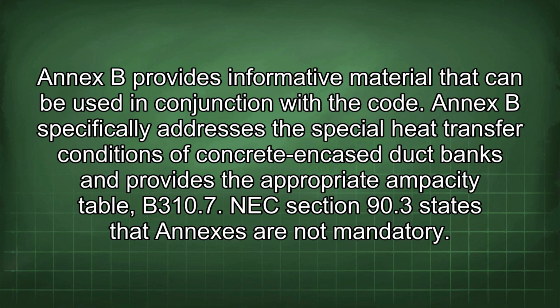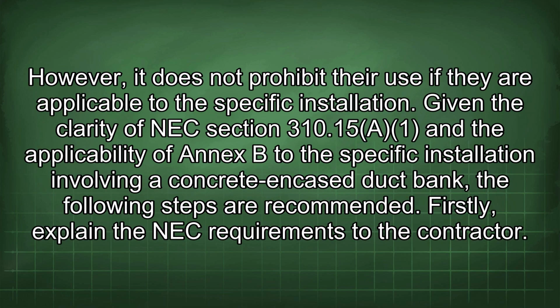Annex B specifically addresses the special heat transfer conditions of concrete-encased duct banks and provides the appropriate ampacity table, B310.7. NEC Section 90.3 states that annexes are not mandatory. However, it does not prohibit their use if they are applicable to the specific installation. Given the clarity of NEC Section 310.15(A) and the applicability of Annex B to the specific installation involving a concrete-encased duct bank, the following steps are